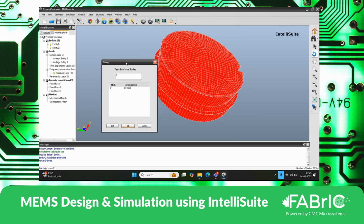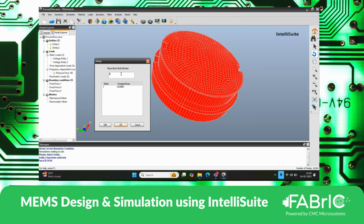Here, damping definition. Since we are working with mode numbers, the modal contribution, so 3 modes of vibration, we generally recommend giving a damping factor, which is editable. By default, I'm just retaining 0.001.